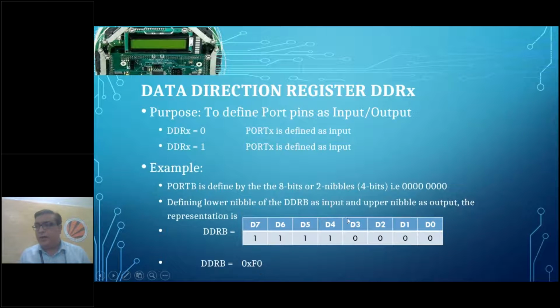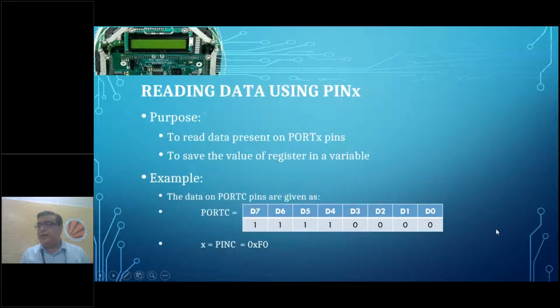Now the second register is PINX. PINX is used for reading the data present on a particular port and saving the value of that port register in a variable.